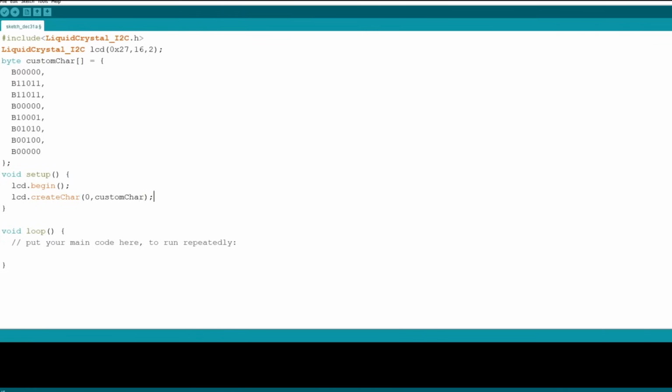And also let's move to a new line and let's call our setCursor function. So let's write here lcd.setCursor and also open and close parentheses and put a semicolon, and let's move inside of the parentheses. Let's define the beginning point, so 0, 0.